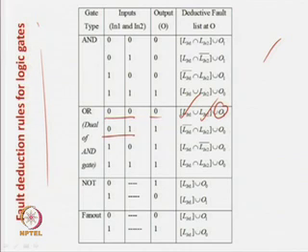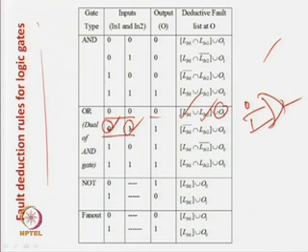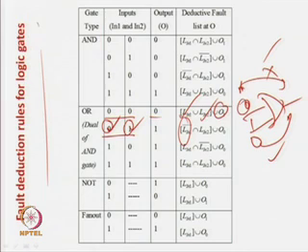0 1. So, in this case, this will allow you to propagate, but this 1 stops. So, whatever is here will be propagated and whatever is here will not be propagated. This is an OR gate. We have a 0 and a 1, so whatever is here will not be propagated over here because this is a 1 and this is a 0. Whatever list is over here will be propagated. So, you write L1 bar, meaning nothing of this area will be propagated and whatever is here will be propagated, that is the intersection, and as 0 1 the answer is a 1 at the output. So, a stuck-at-0 fault at the output will be detected.